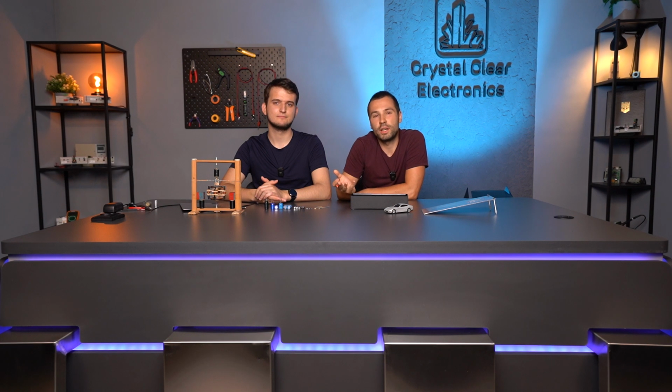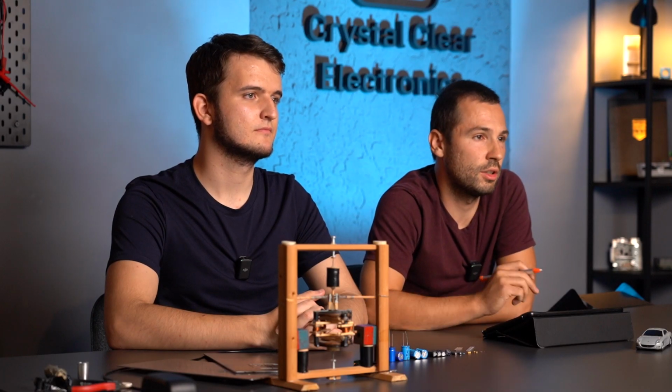I will now talk a little about the electrical sources that provide the energy needed for the charging current. In electronics, we distinguish voltage source and current source. A voltage source is a device whose voltage is constant between its electrical terminals, even if current flows through it. In contrast, the current source changes the voltage between its terminals so that the characteristic current flows through it.